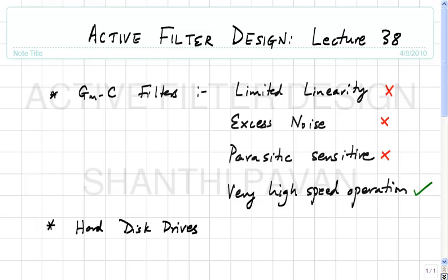The signal is also very small, so before the DSP can process it, please note that it's not a clear 1010 that you can read off directly into your CPU, right. It is a very small signal, probably several tens of millivolts, and by visually eyeballing it, you will not be able to make out any data pattern at all, right. So what is done is to use an algorithm which is very common in most communication systems today. This is called maximum likelihood sequence detection, and the algorithm used to do it is what is called the Viterbi algorithm.